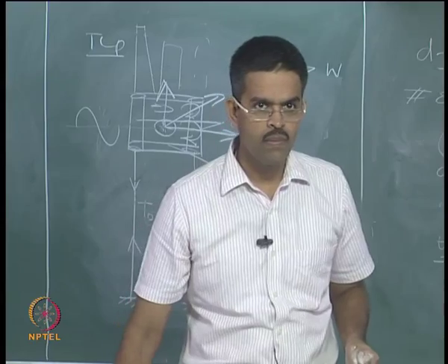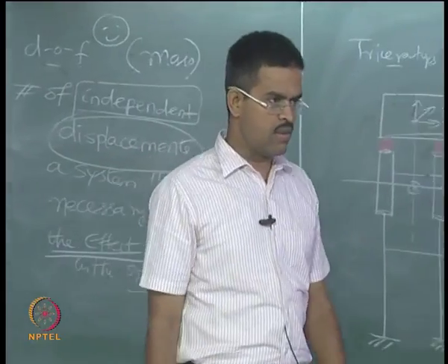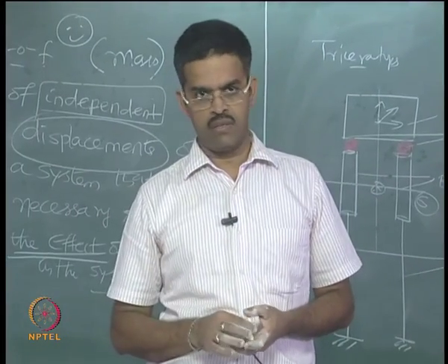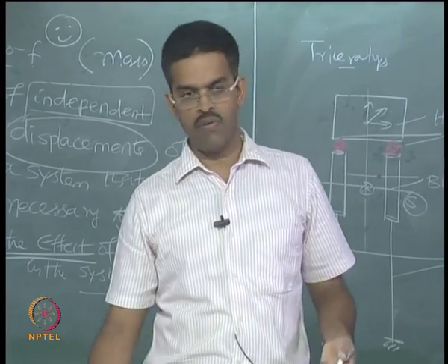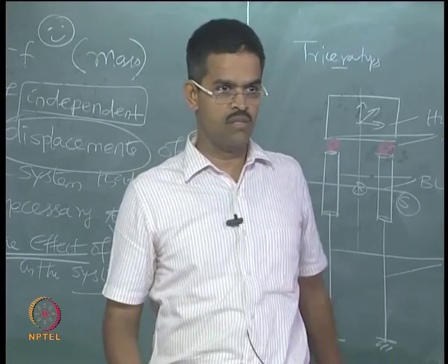Sorry? So, it is coupled with the acceleration term. So, mass and acceleration will give me the inertia force, that is fine. So, why not any other term? For example, stiffness is coupled with displacement, that is also a derivative of acceleration. What poor thing the displacement has done, so that people talk only about the inertia force. Why inertia is important in dynamic analysis?